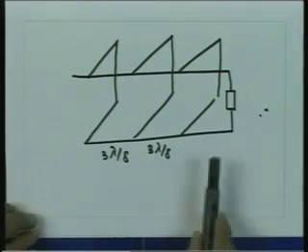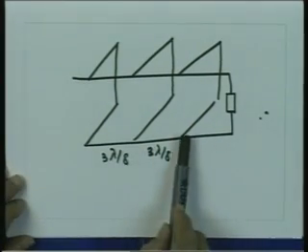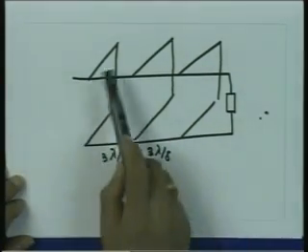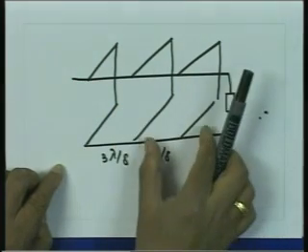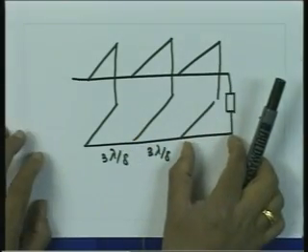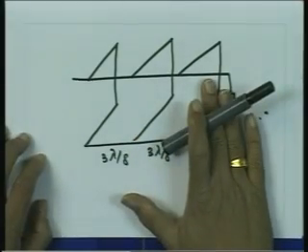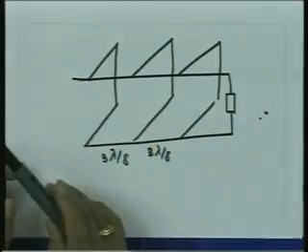The matching is again double stub, but if the matching is done with these 2 stubs, I can make this one open circuit by choosing its length equal to a quarter wavelength. If I find that by choosing these 2 stubs, the transformed impedance lies in the forbidden region, I can disconnect this stub and make use of these 2 stubs. So depending upon whether the transformed impedance lies in the forbidden region or not, either I can make use of these 2 stubs or these 2 stubs.